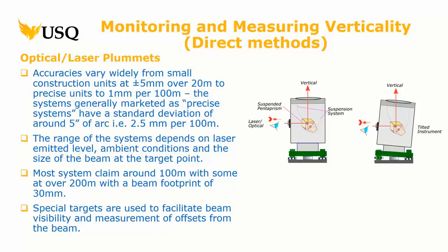And you'll see quite often the targets are bolted into the floor, and they've got scales on them. So when you measure up, you can actually see the scale. You can see the beam point, you know how far it's off. And then you put a mark on there for the center, in other words, the most precise point from that point to the point vertically above you.